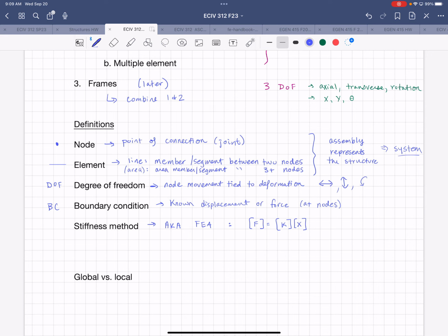And continuing on with that, in fact, if you have an indeterminate system, or I should say the more indeterminate the system is, actually the easier the solution becomes. Because the more indeterminate a system is, the fewer unknown displacements you have, right? Think about that. Fewer unknown displacements you have, the more indeterminate the system is.